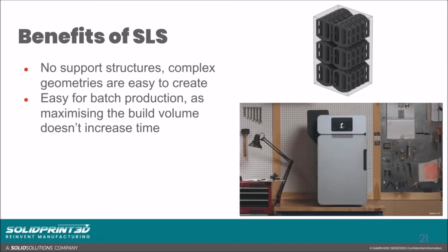What it means is that batch production can really be maximized. As soon as you put one part into the build volume, the entirety of that height worth is going to tell you, let's say, for example, 10 hours. If you were to fill the entirety of that build volume to that point with the same part, as you can see in that top right hand side image, it's going to be 10 hours across the entirety of it. As I mentioned, it's that scanning process you'd imagine on a normal 2D paper scanner. It allows us to go through that one flash of laser, one flash of light, effectively doing the curing for us, allowing us to really maximize it.